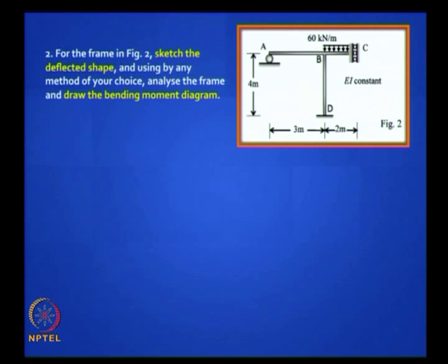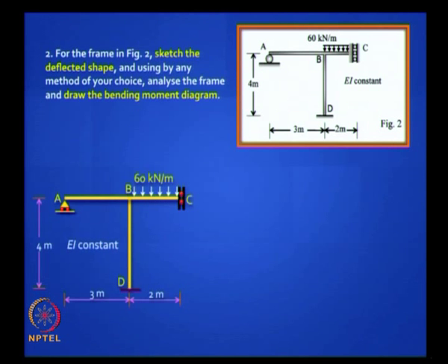Let's move to this problem which I asked you. Some of you did it right, some of you messed up. When I asked you to draw the deflected shape, many of you lifted up the beam from A. There's a roller support there, how can it fly up? So this was the problem given to you. There's only one unknown rotation here, okay. First of all you should do it by the displacement method, because you know that this is the power of the displacement method. Force method is a crazy thing to do here.